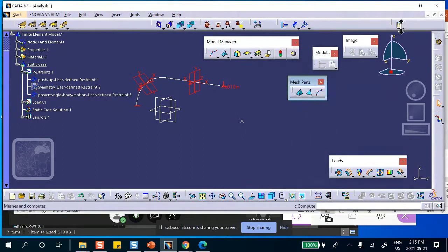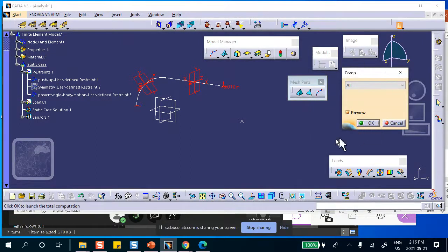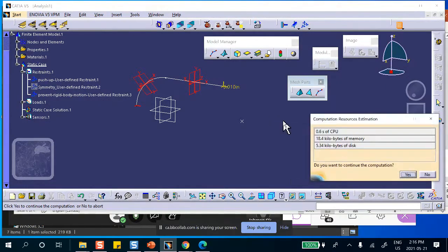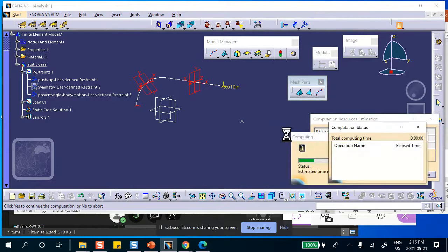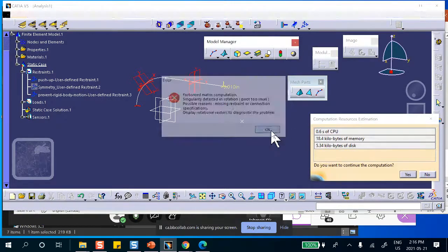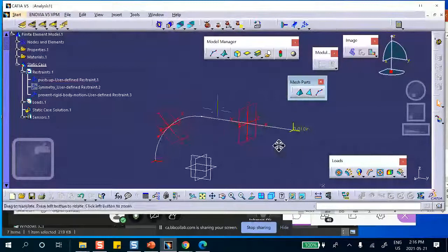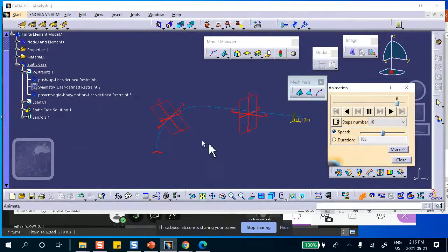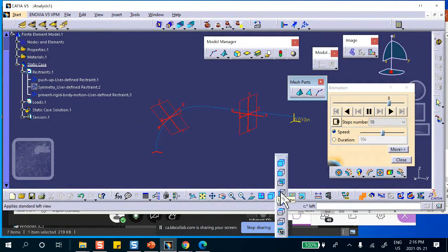Not quite. Let's run it and you see what happens. There's something else that we have to do. We did most of the work. Most of the work is correct, but as you can see, not the whole thing. If you look at the display, this deformation, and animate it, you see that we did not take away the rigid body rotation about the z-axis, and that's what's happening. But if you look at the view from the top, for example, where's the top?